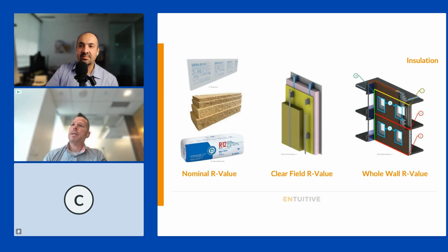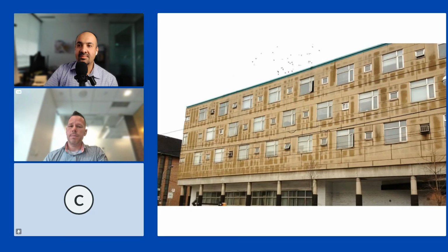I refer to this as return on investment. So everyone loves to talk about money, and I want a good return on my investment if I invest in the stock market or I invest in a company or a product. I'm investing in insulation. I'm investing in an R12 insulation. If I have a steel Z-girt on the outside of my building, I'm getting a 50% return on my investment. I'm basically losing at least 50% of my value that I've spent on that insulation because of thermal bridging. So it's very important to focus on these details.